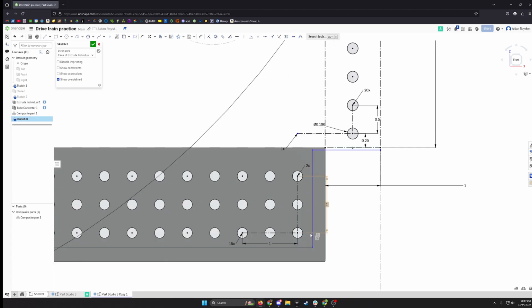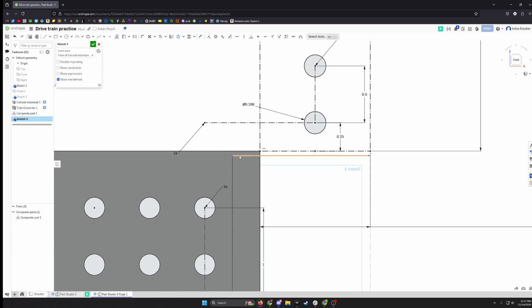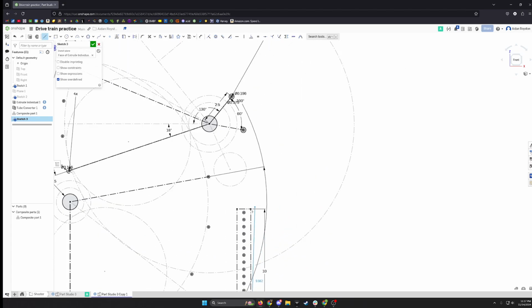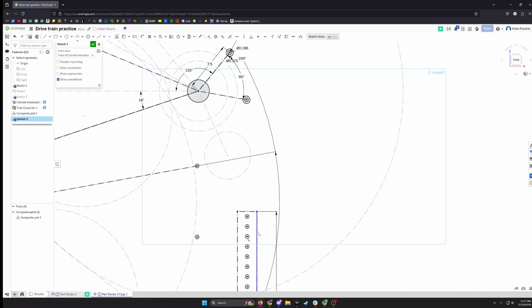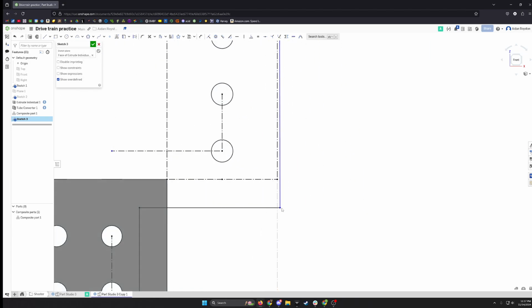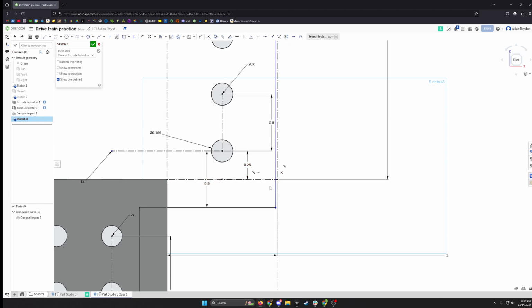I'm going to come over here, and we're going to do the same thing, 1/4 inch. And we want to come over here, and let's make this one a little bit longer. Let's make this one 1/2 inch. And we'll just have this line come up to the very tippy top of this bar reference geometry. We see it's going to move like this. You can just drag it coincident, just like that. It's not like that. If you see something like that happen, just Control Z and try something different. We'll just grab these two lines and make them coincident.